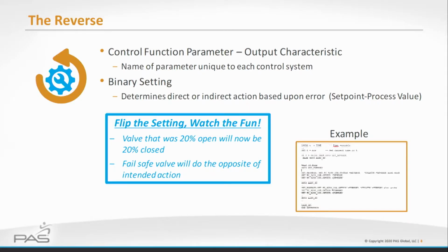In most control systems that you get, there's things called functions, okay? A control function, like a flow controller function. It's like a piece of compiled code that you grab off the shelf and you configure it with your information about your process. Like here's the ranges of the process we're in, the engineering units, like am I looking at gallons per hour or gallons per minute, alarm information, all of these things that you configure to make that control function work. In this case, a flow controller.